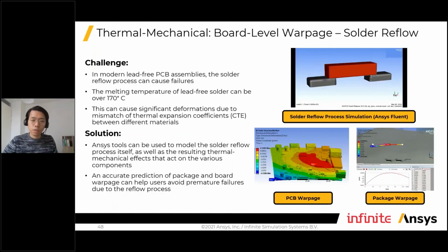Oh, sorry, one slide's been jumped. So this is the reflow process, as you can see, modeled and simulated in Ansys Fluent. And then we also have the thermal issues, and then the package warpage during the reflow process because of the mismatch of the thermal expansion coefficient.